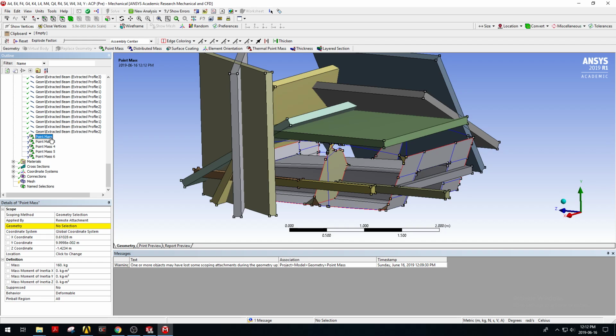In order to get the proper simulation requirements, which is collisions at 5 Gs, I need to accelerate it at 5 times 9.8 meters per second squared. Then with the proper mass, you have F equals ma. So you have the proper mass of your model and the 5g acceleration, and then you can get the proper force you want applied on your model.